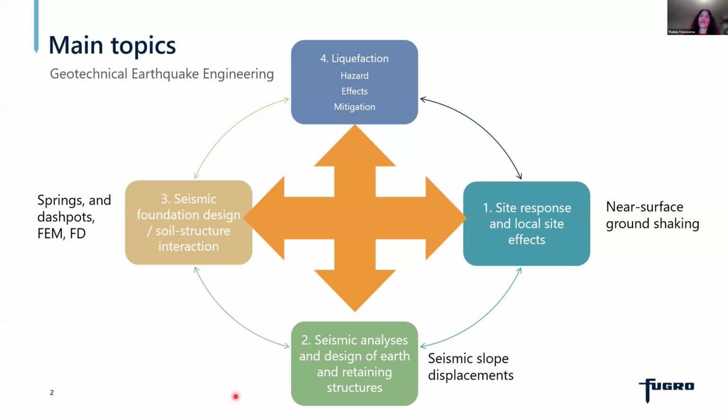The third would be the seismic design of foundations and soil structure interaction. And here, traditionally, geotechnical engineers come up with springs and dashpots or perform coupled analysis with finite elements and finite differences. And the fourth is the very wide and broad topic of soil liquefaction, that can also be subdivided into subtopics that include the liquefaction triggering hazard, evaluation of liquefaction effects and associated demands, and mitigation.